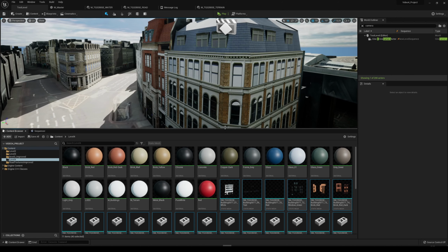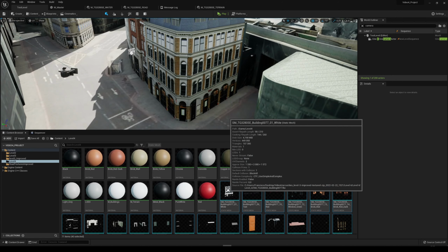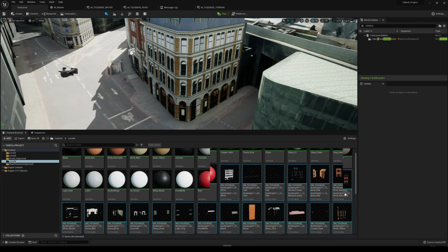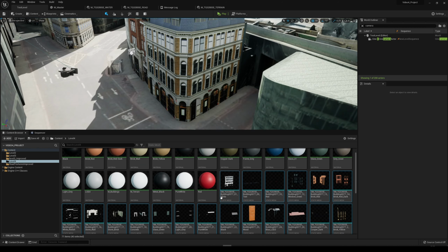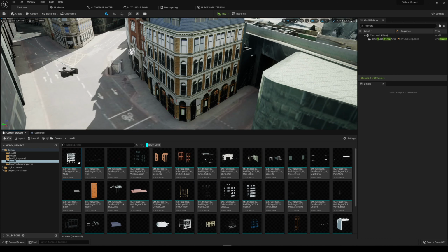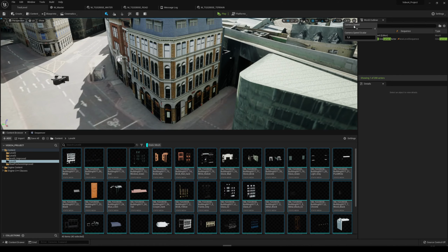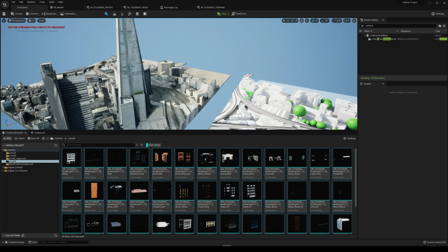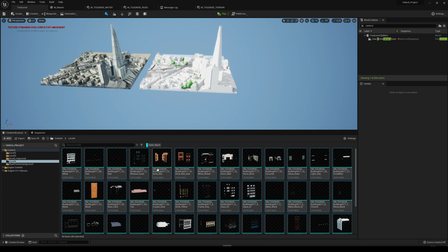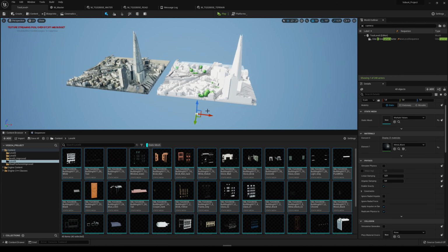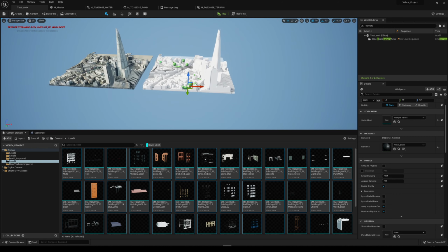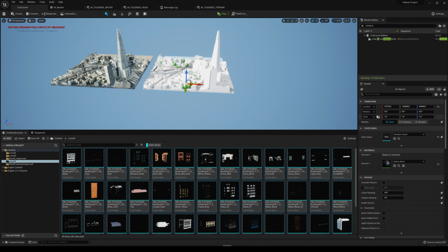let's actually go into our level 4 buildings. So yeah, you can see that I have all the static meshes selected. I'm going to go up here, select all the static meshes. I'm going to select them all. Let me go into speed 8, and I'm going to drag and drop my buildings here into our scene. Drag them all. You can see that we're going over our texture streaming pool budget a little bit. I'll tell you how to disable that in a second.